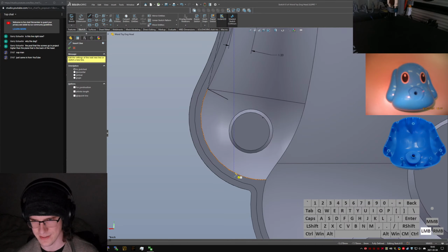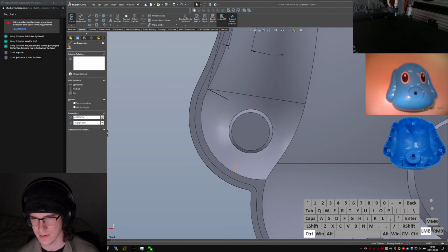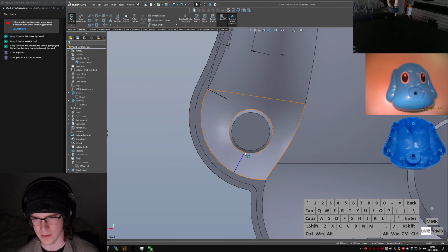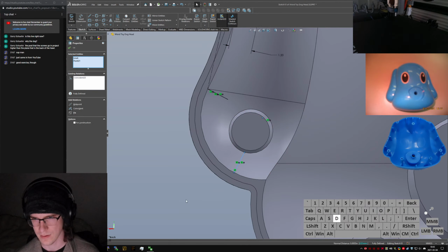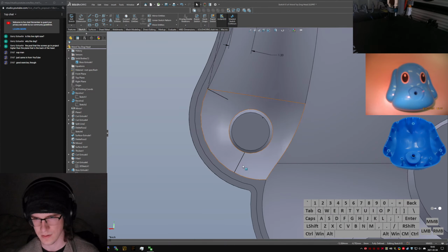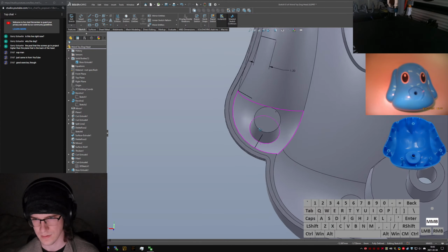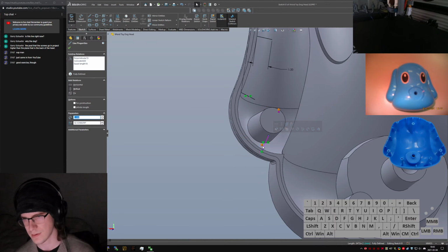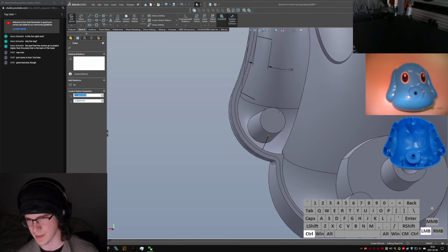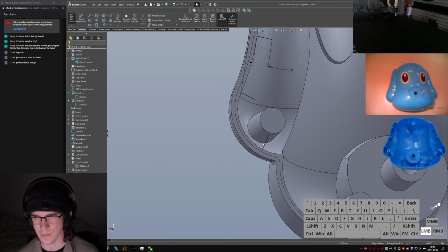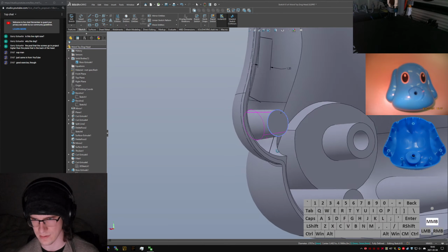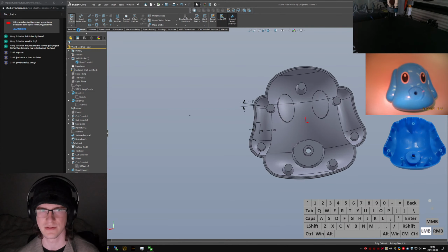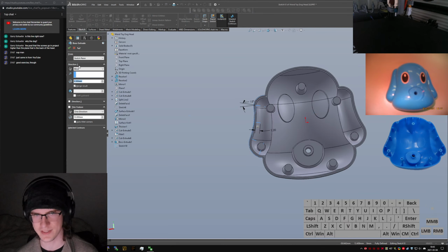All right, let's do one more over here. Same length. Let's do equal and perpendicular. And also coincident. You know what? Rather than being equal length, I'm going to make this coincident with this line so that I get sort of a guaranteed boss through there. Ooh, I should test this to see if it actually works.